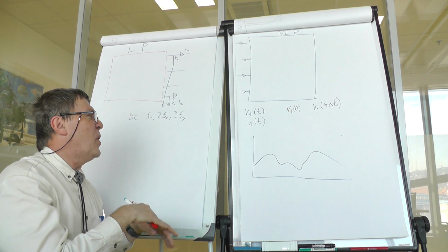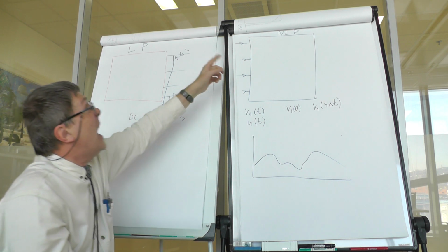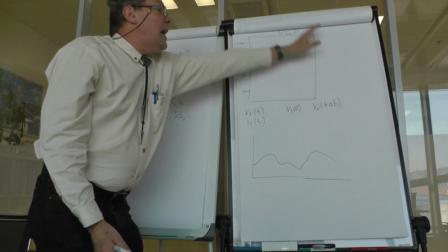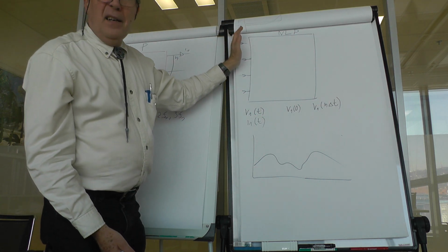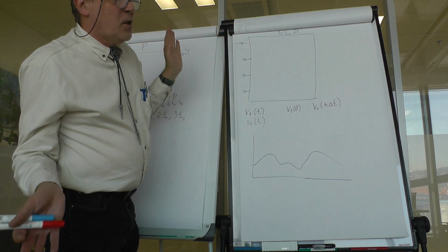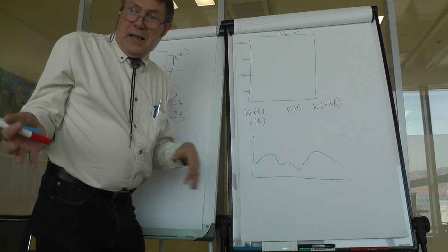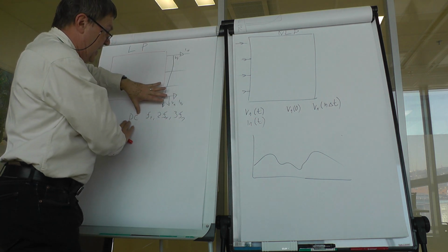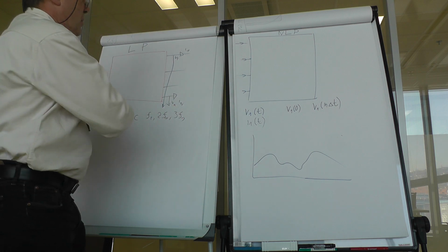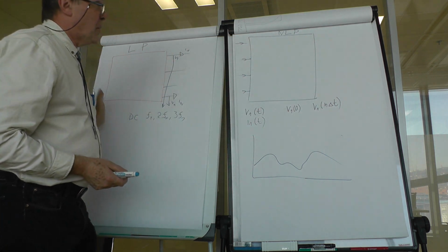Now there are a number of tricks. The first idea you would possibly have is: I have tried to put here 1 volt, and after the loop 2 volts came out. Well, what about trying to put there the average, 1.5 volts? Now, yes, this would possibly be easier at the harmonic side, so you can start the process here or there. What you want to achieve is the harmonic balance.